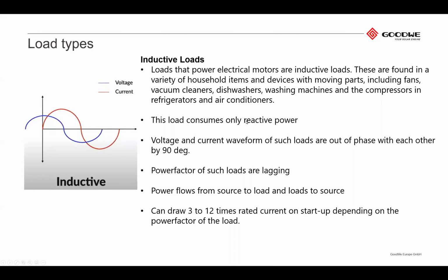It's something that's always overlooked because it's generally not worried about when the grid is available, because the grid absorbs this. The load time is normally very short, 2, 3, or 4 seconds, and then that large spike is passed. So when we connect it to the grid, it's not a problem at all. But when we only have batteries available and our overload time is only 2 seconds, this large spike does cause an issue.